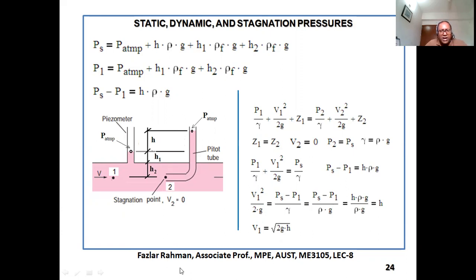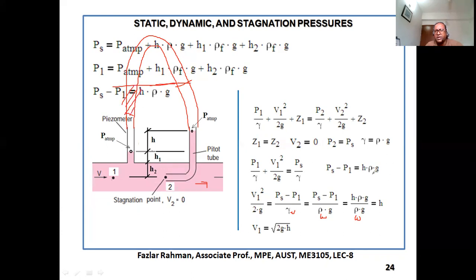Now, if I attach a tube in the manometer, say inside water is going, so this will be gamma water. Right here will be gamma water, right? And this deflection, instead of having the same fluid, if you put mercury, then your deflection will be this much. Then this fluid will be rho mercury, rho m. In that case, your G will be out. Then there will be one more term, rho m divided by rho water, since water is flowing inside the pipeline.